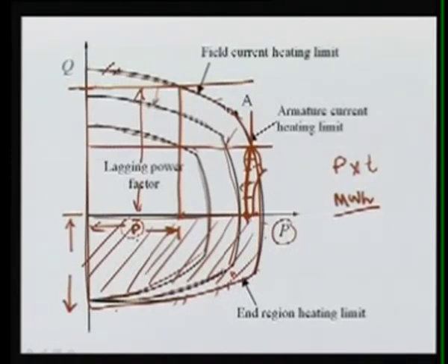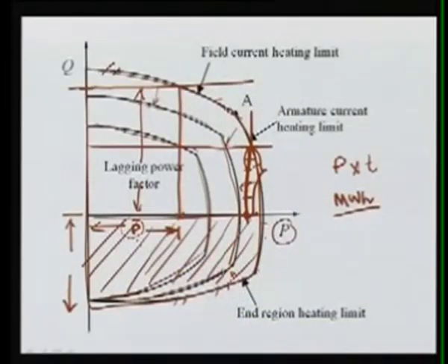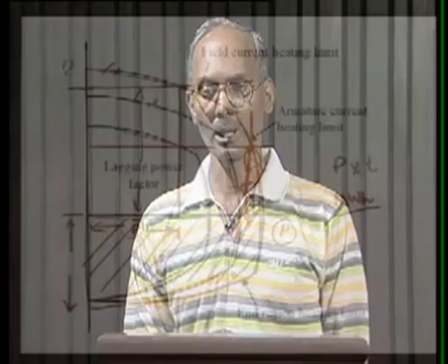So this zone is only utilized when there is a black start, when the generator is going to start its power after a blackout, meaning it is going to synchronize with the transmission system. Then we can ask the generating company to absorb, because the generation of reactive power through the transmission line is more at that time.